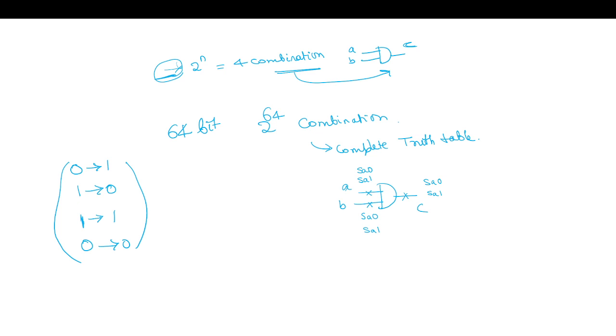If we consider that it is sufficient to test the primary inputs, then A stuck at 0, stuck at 1, B stuck at 0, stuck at 1 should be sufficient.